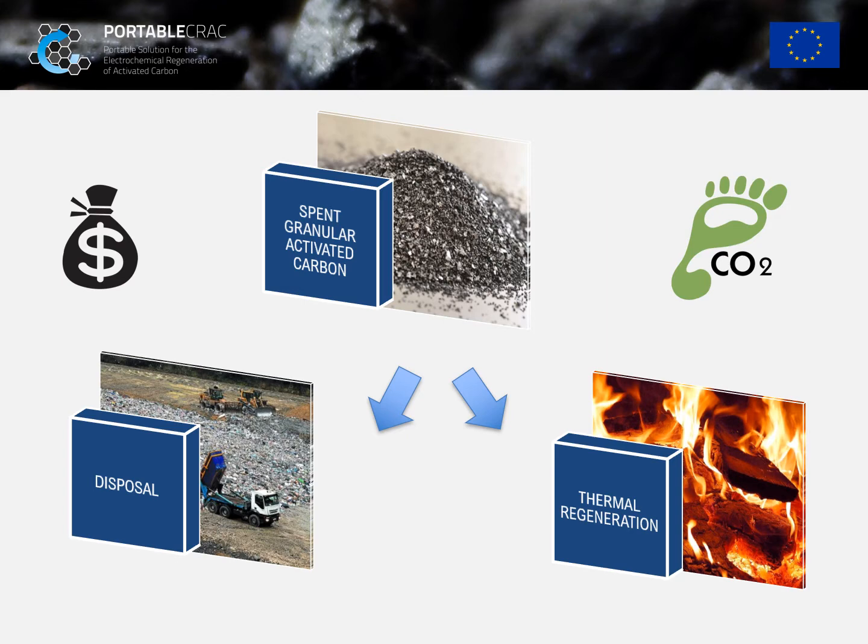During the use of activated carbon to retain contaminants, the porosity becomes progressively saturated and inactive. In small facilities, when the carbon reaches its saturation limit, it is usually taken either to a landfill or to an incinerator. However, in facilities where a larger volume of carbon is used, the preferred option is to regenerate it through a thermal process.